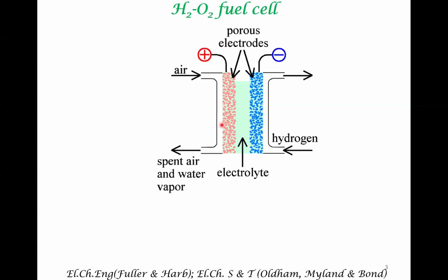This also tells you other issues that are relevant for the commercial prospects of fuel cells. The overall cost must be less. Therefore, many approaches to decreasing cost have been attempted when it comes to commercializing fuel cells. For example, instead of sending in pure oxygen, you supply air. But when you do that, air might have other impurities like CO2. This CO2 might react with the alkaline electrolyte.